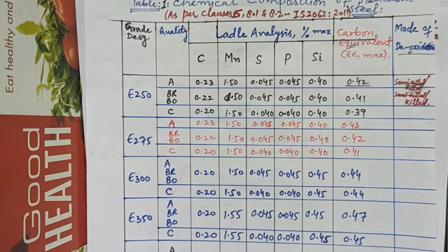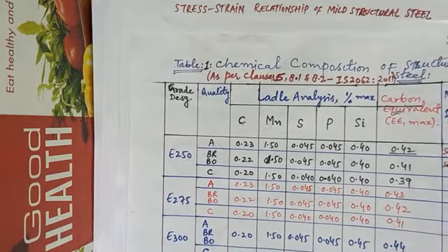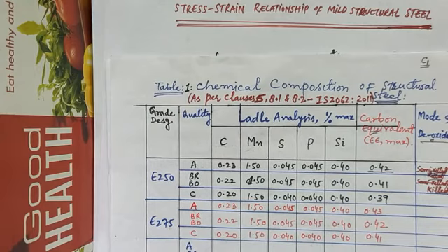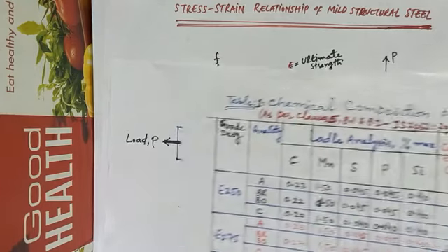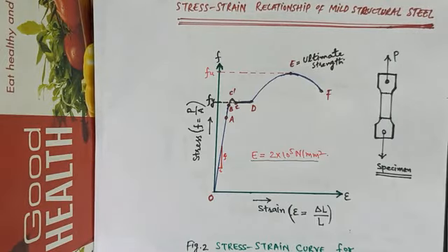Indeed, satisfactory steel design methods cannot be developed unless complete information is available concerning the stress strain relationships of the material being used. Undoubtedly, the tensile test is the most fundamental type of mechanical test performed on structural steel. So, the information needed for the structural design of steel is mostly obtained from the stress strain diagram of steel.